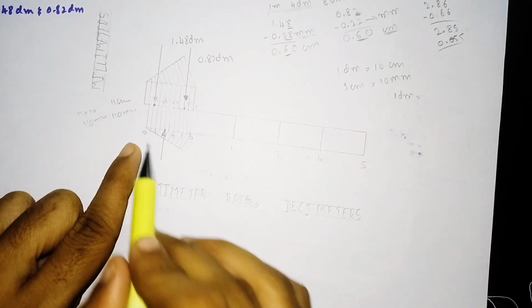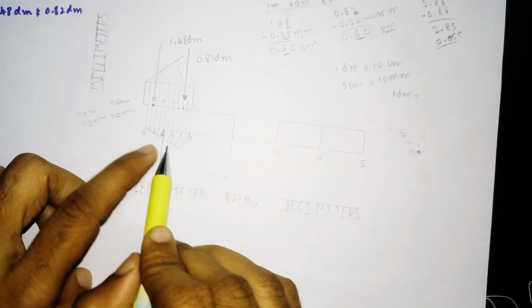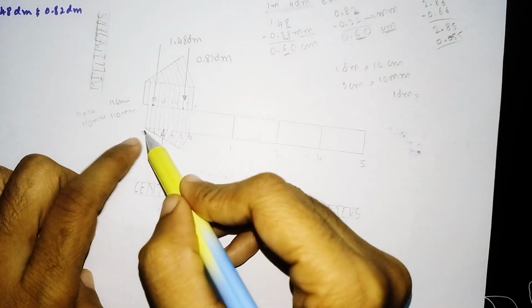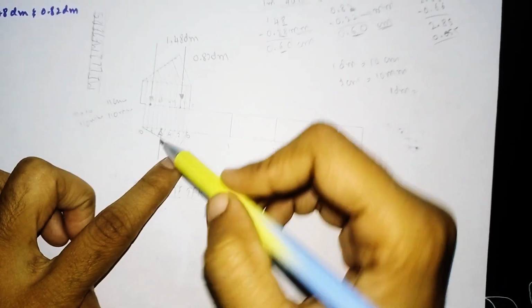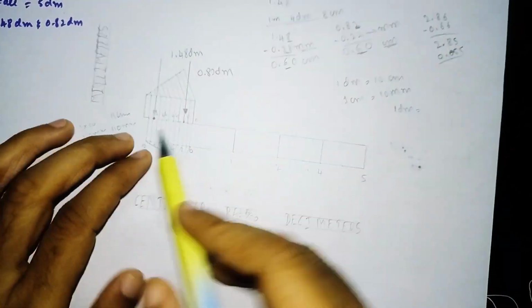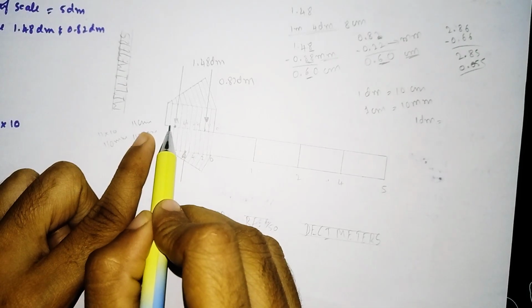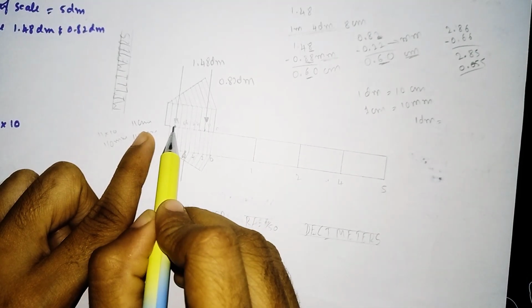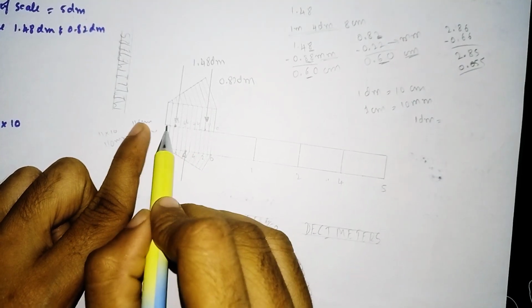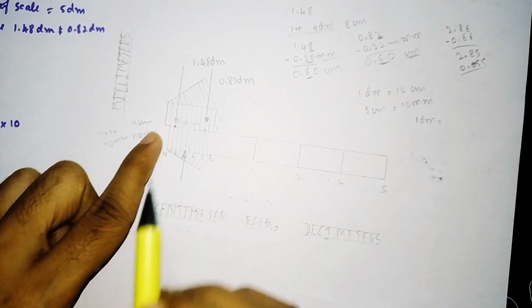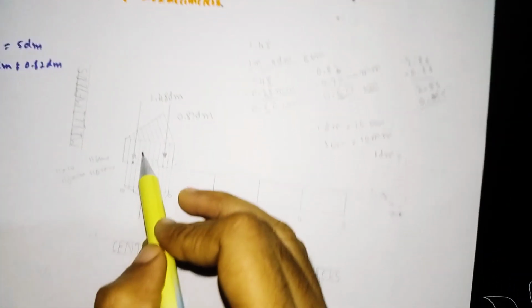And before that, for that we have to go for the inclination method. I have drawn one inclination of 2 centimeter, and here I have marked the 0.22 mm, and I have drawn the lines, and again I have joined this to here. And later, when it comes to the vernier scale, I have extended this line by 0.2 mm, whatever the length of this division. So I have extended the 2 mm. This from here to here is our 10 centimeter, it becomes our 11 centimeter.